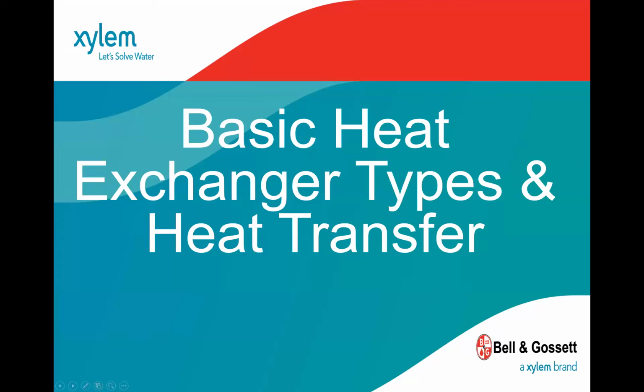The whole point is that on the left-hand side, you'll notice that we have a counter current. On the right-hand side, we've got the co-current, where the hot and cold are going in, the coldest and hottest starting together, and they're leaving. If you take the approach of the hot and the cold, or the exiting and entering for the co-current, and look at the log mean temperature difference we calculate, you'll notice that the reduction in the LMTD would require essentially 25% more surface area.